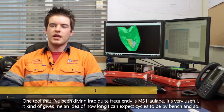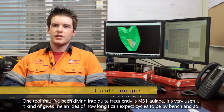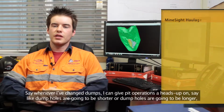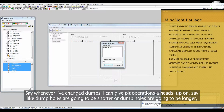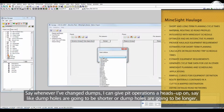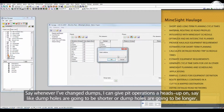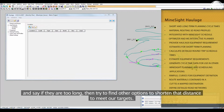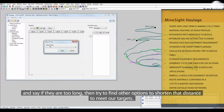One tool that I've been diving into quite frequently lately is MS Haulage. It's very useful. It gives me an idea of how long I can expect cycles to be by bench, and whenever I change dumps, I can give pit operations a heads up on whether dump hauls are going to be shorter or longer, and if they are too long, try and find other options to shorten that haul distance to meet our targets.